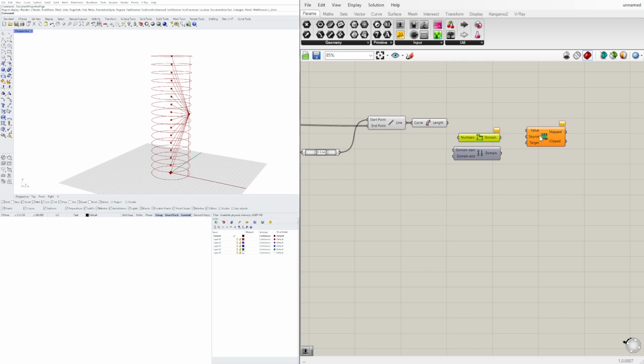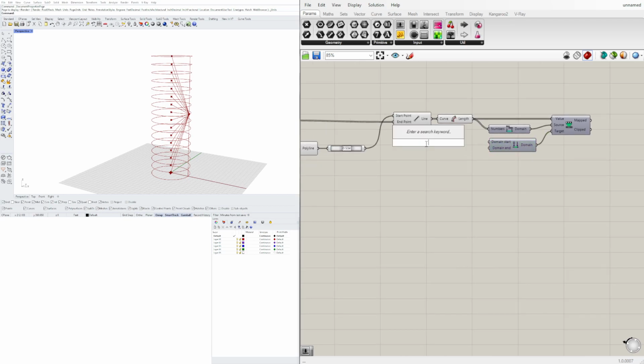And this middle one, source, is going to be bounds, so the biggest and smallest number, and then value is going to be our original numbers. So our original values go into the value input, then all of these values go into the bounds to give us the biggest and smallest number, and lastly, we get the length to plug in the start and end number. Plug that into the target, and since we're doing a scale, it has to be smaller than 1 or larger than 1.